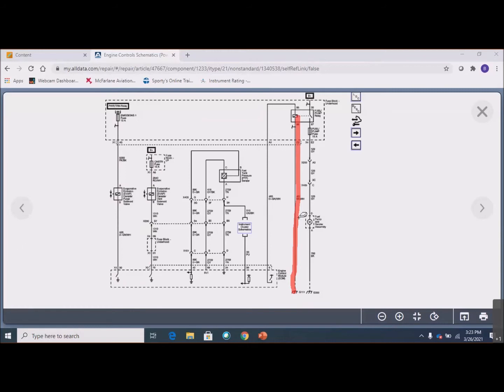And in order to energize it, what happens is the ECM, remember I said this little bar represents power, right? So the ECM connects that power to this circuit. And since the relay already has the ground here, right? So now we have a complete circuit and the relay energizes and current flows through the switch contacts. So again, power side switching here, ground side switching here. Ground side is much more common, but it's not exclusive.